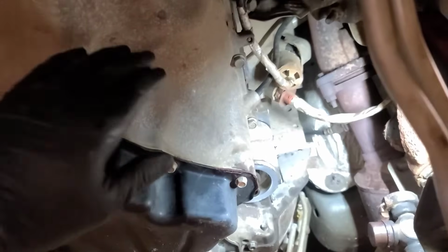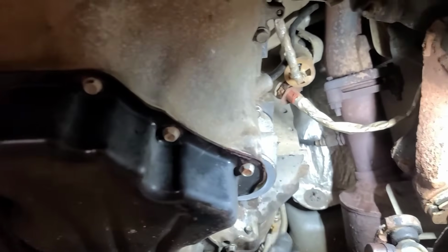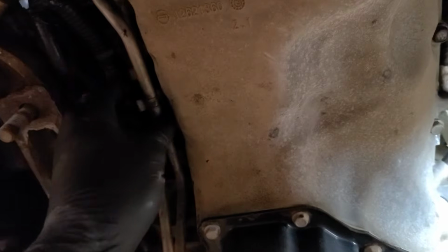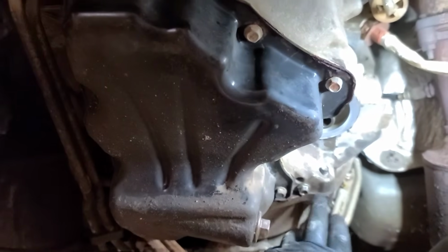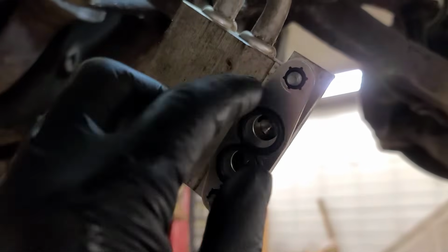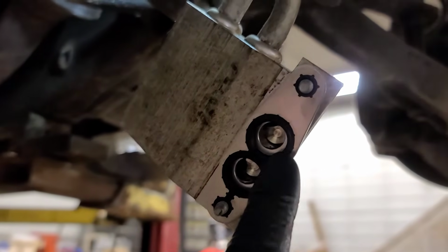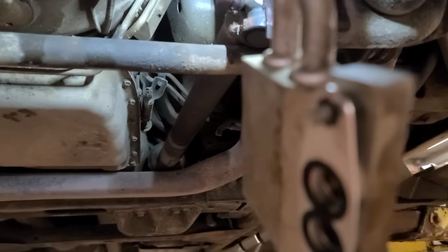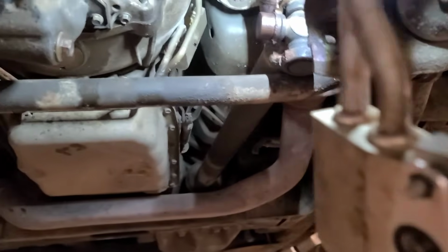So there's the oil pan reinstalled. This cover back on, the one on the starter back on, the bracket holding the cooler lines back on, two rear bell housing bolts in. Now we're ready to put the oil cooler adapter on. Make sure you get the gasket in correctly. I see it could go in both ways, but obviously it's offset accordingly. And yeah, that's it. We just keep going.